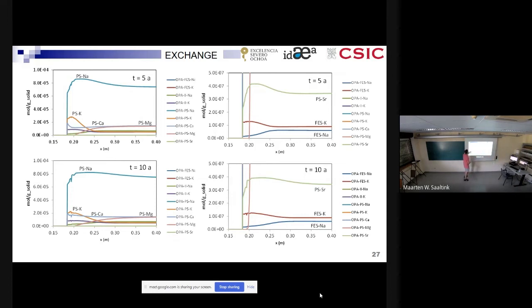With time, this is kind of relaxing, little by little going back to normal values, because basically potassium and sodium are displacing everything else, but mostly you only have a limited amount of it. It's only in the pore water, so you only diffuse a very finite amount into the clay. And actually once this is lost, then there's no more sodium and potassium. So little by little, this effect is recovering. Things are going more or less back to normal, and this amount of sodium and potassium diffuses into the volumes. So things recover gradually. And so that's the ion exchange.